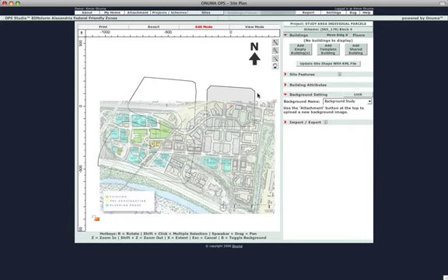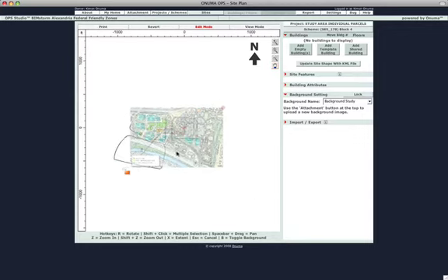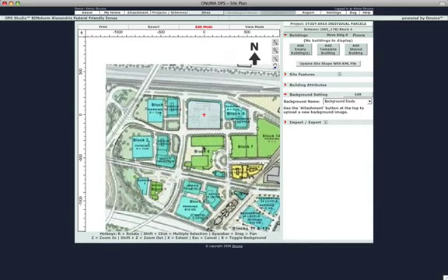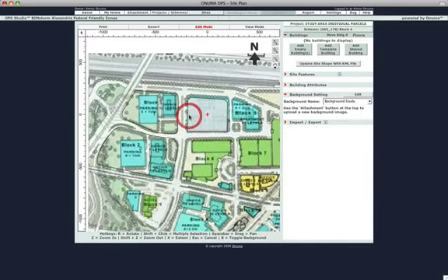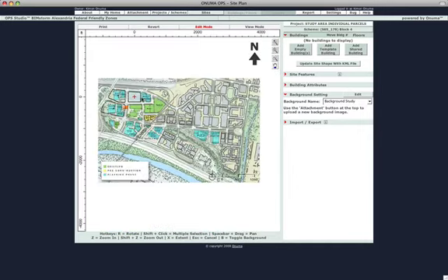stretching it out. We're going to use those 3 reference blocks as a scaling factor. So they're up in the upper left, so we need to stretch this quite a bit to get it into scale. With that, we have it in scale now, and I'll lock the background, and you'll see the polygons on top of the blocks, which are actual shapes, and we're ready to start placing buildings on this site. We have the other part of the image as a JPEG for reference in our work and study in this area.